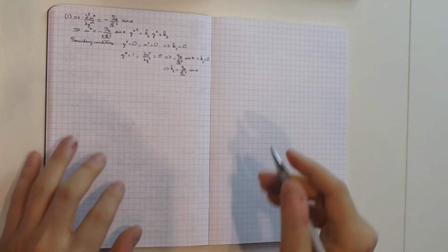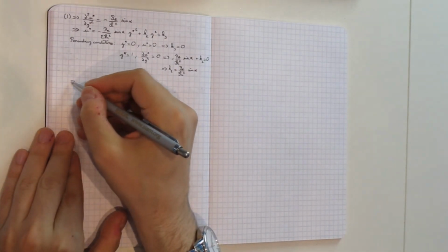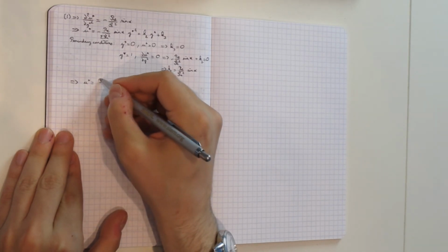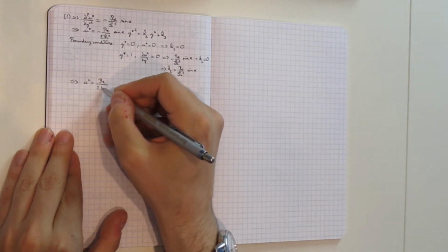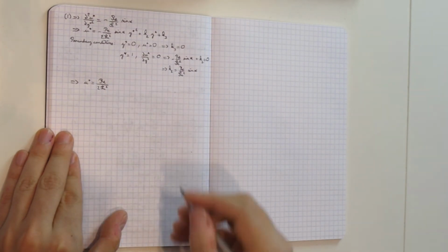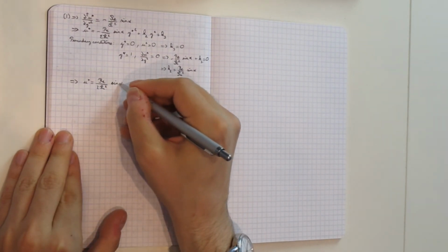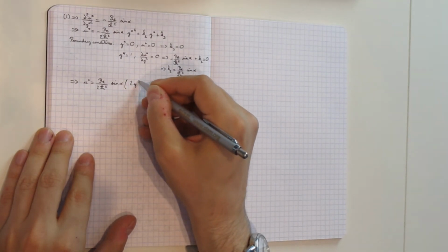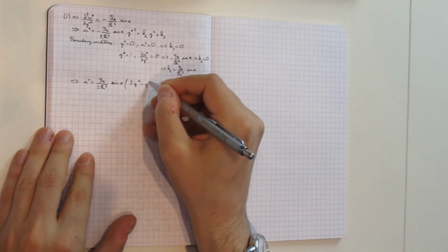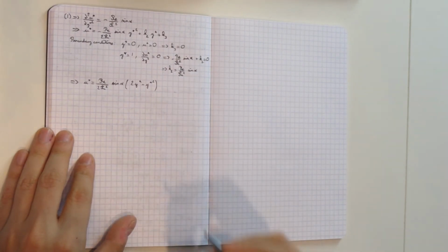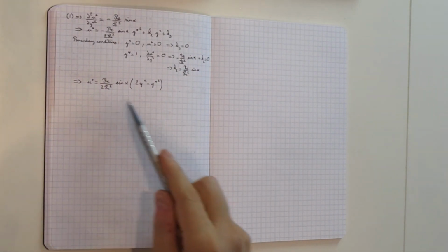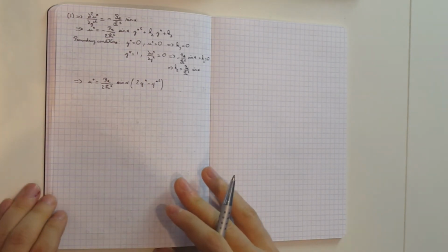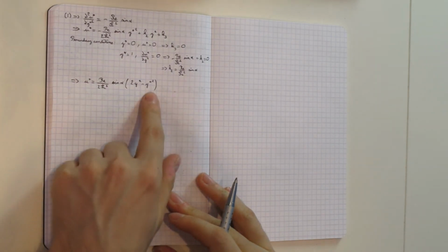And so we can put that all into the velocity and write down the final solution of our problem, which is the Reynolds number over twice the Froude number squared times sine alpha, and I'm going to have 2y star minus y star squared in my parentheses. And so this is our velocity profile for the flow down an incline. And what you can see here is that this is a quadratic function.